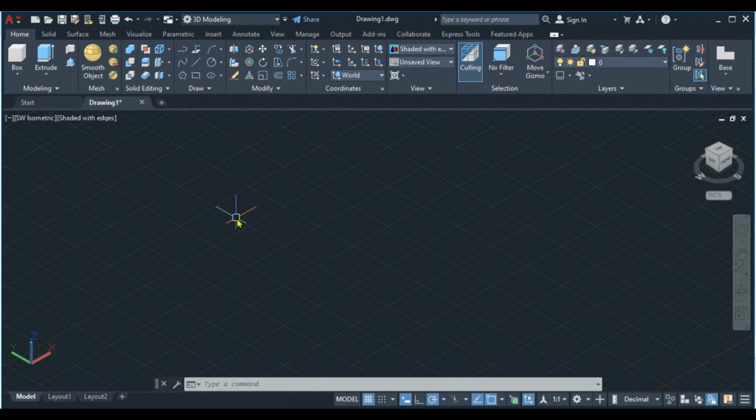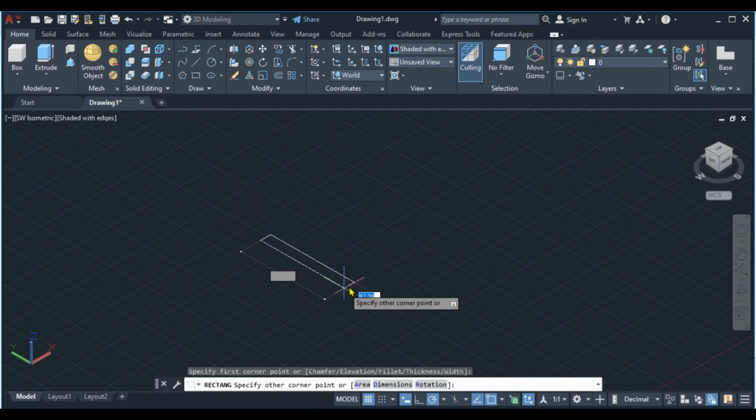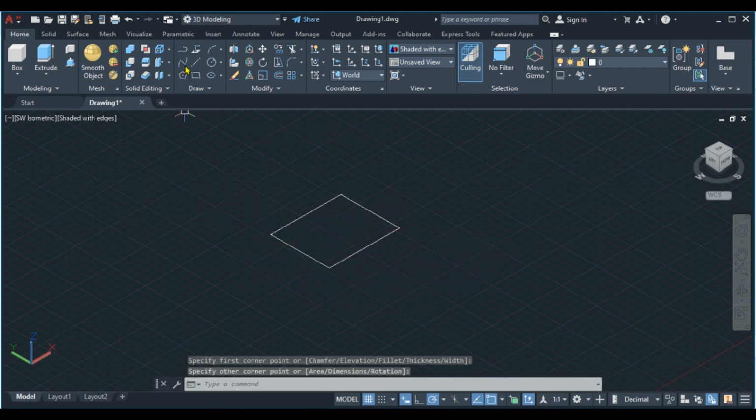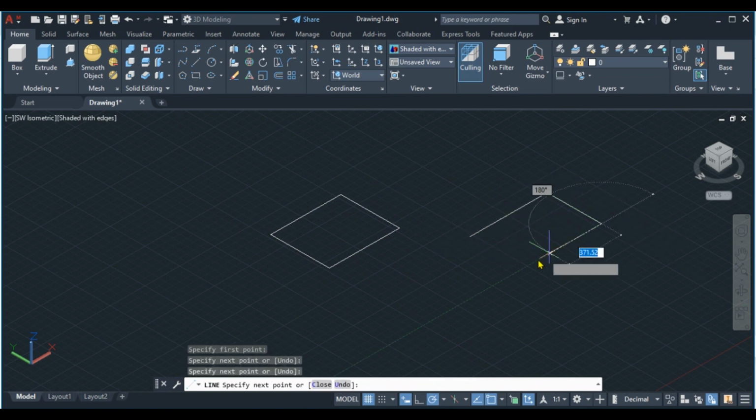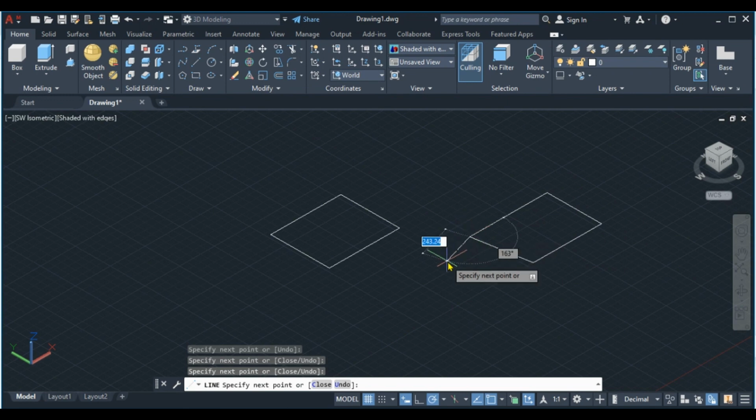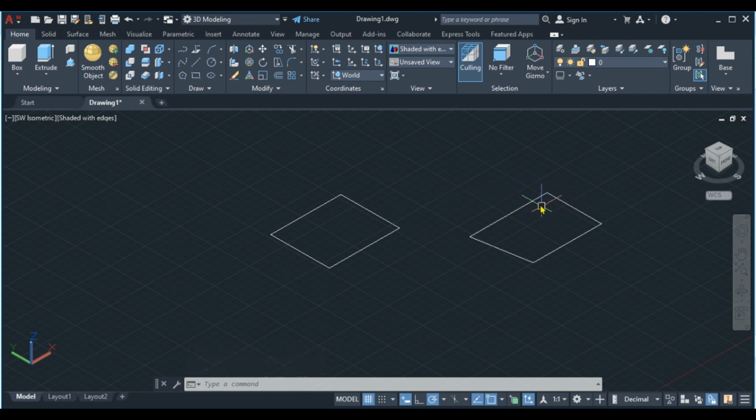So in today's lesson, we are going to learn the press pull command. Now remember with the extrude command that we learned the other time, we saw that, for example, if you have a shape like this and you have, let's say, a line drawn separately in this orientation, before you can actually extrude, you have to make sure you join, right?